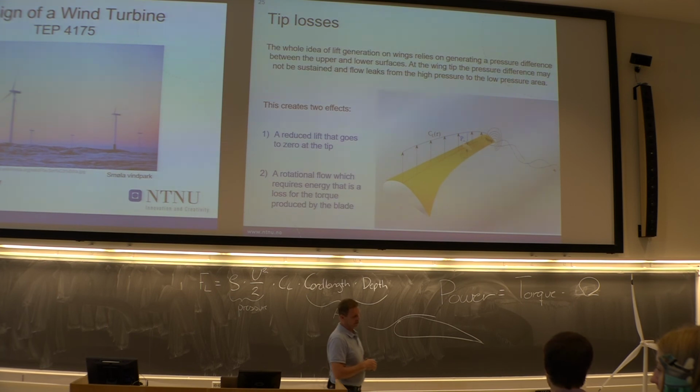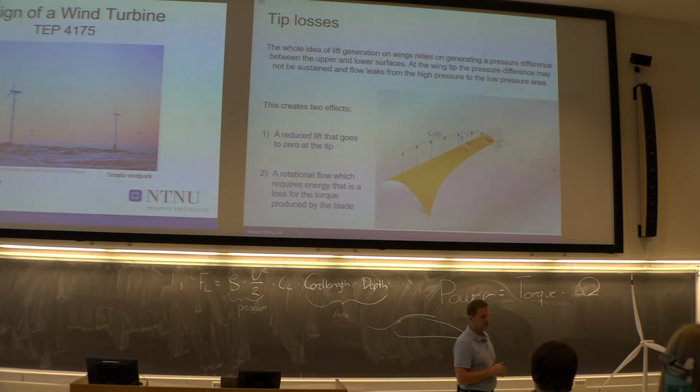Another thing that some of you, I want you to consider to include into your calculations are the tip losses. If you have an airfoil and you have a pressure difference between the upper and lower surface, at the tip the air might take the shortcut from the highest pressure to the lowest pressure. And that's the tip loss.